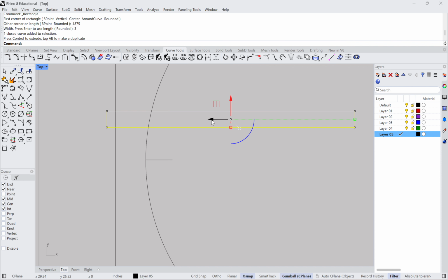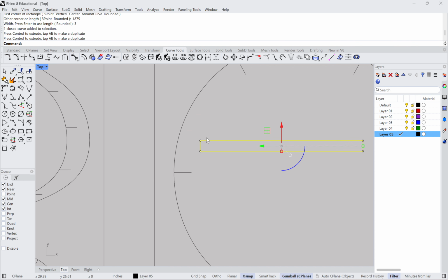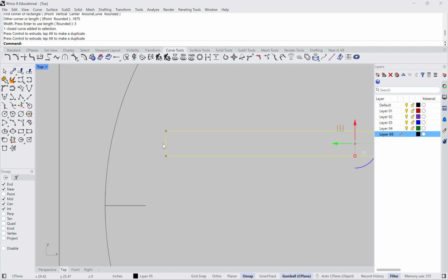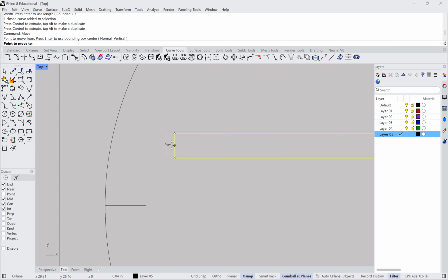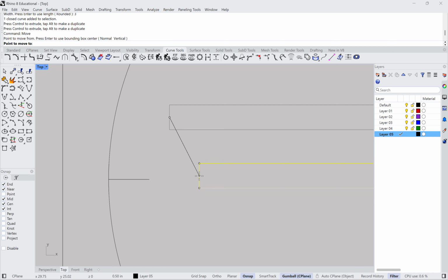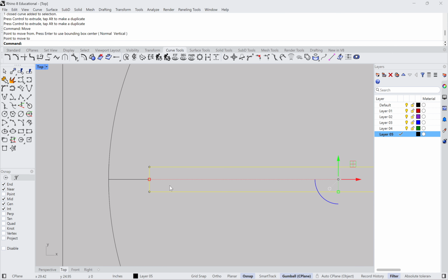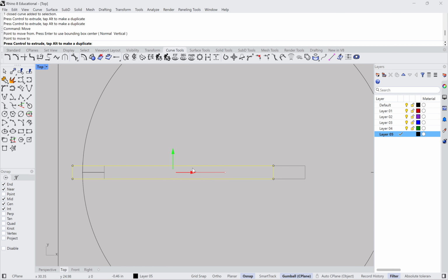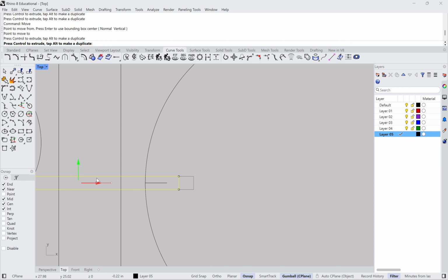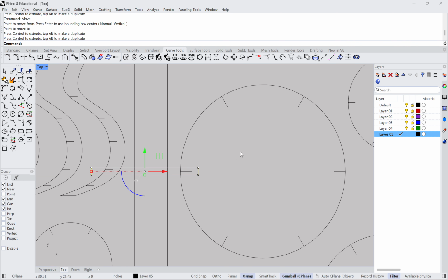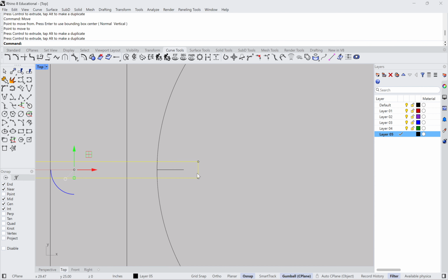So with this material thickness, the 3/16 of an inch, I'm going to move this rectangle from the midpoint on one line, get it on an end, and then slide it back until I have enough of that shape entering the circular wooden body.